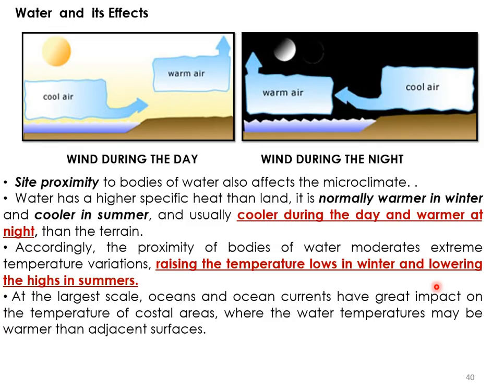And we have water, which is a very important part, which can give us a variable microclimatic condition. If you look at any location which is near a water body, the climatic or microclimatic conditions will vary. If you see the concept of this during the daytime, generally what happens to any built structure near the water body is that the warm air tends to go up, and the cool air from the water body, due to the evaporation, tries to push inside the land. This is the natural phenomenon which takes place during the daytime.